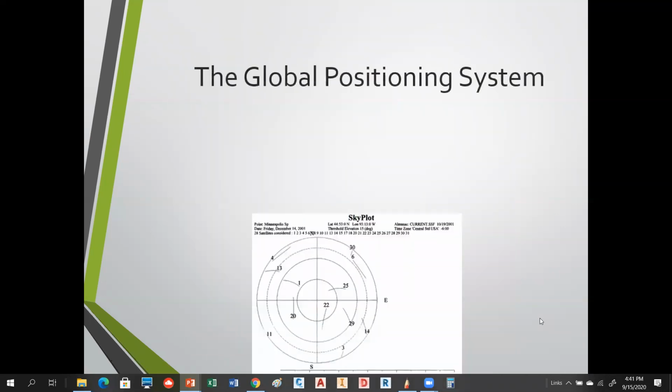And this is called a sky plot, if anybody's never seen one of these before. And a lot of times your controllers will show you this. You can pull these up on a controller. So it'll show you, you're basically at the center, and this is showing you your horizon, and that dotted line, that's your mask. So basically from horizon to mask, it says even though satellite 6 is available during my time of occupation, it's masked out.